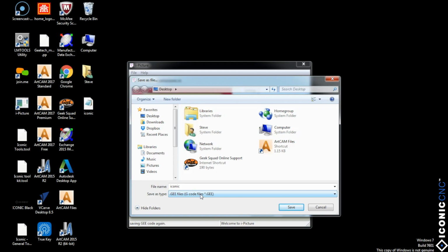The other thing, actually the most common mistake that it avoids, is if I misconfigure the material. So I've got the right size material, but I put it in the wrong way. So I designed a project 12 by 6, but inadvertently I mount the material in the table 6 by 12. And once again, the machine thinks that the material is 12 by 6, so it's going to machine where there is no material. And sometimes there's a clamp in the way, and that can be a problem.